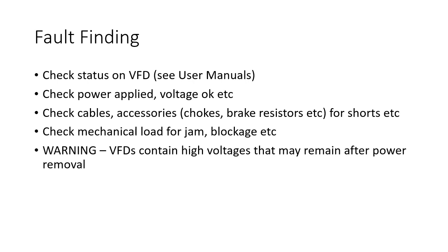And they're also DC voltages. DC voltages are particularly problematic because with an AC voltage, you might still be able to get an electric shock and move away. But with a VFD and DC voltages, if you get an electric shock, all your muscles are locked in place, and you can't release yourself. Once you get that high voltage shock, you're stuck to it until you suffer a very high level of injury and die, or until someone turns the power off or levers you off, hopefully using some sort of wooden implement so that they don't get an electric shock themselves. So be cautious, very high voltages, be very, very careful around VFDs.